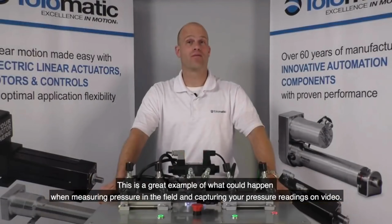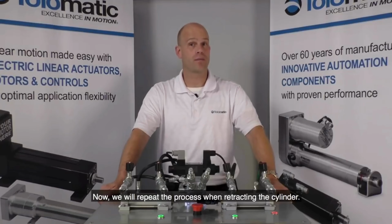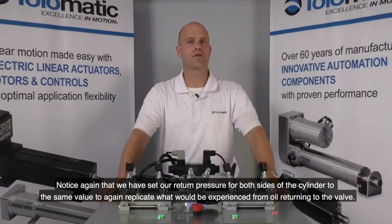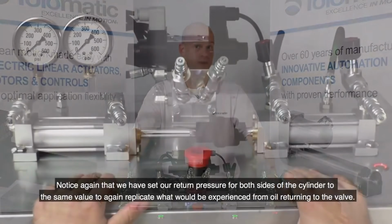This is a great example of what could happen when measuring pressure in the field and capturing your pressure readings on video. Now, we will repeat the process when retracting the cylinder. Notice again that we have set our return pressures for both sides of the cylinder to the same value to again replicate what would be experienced from oil returning to the valve.